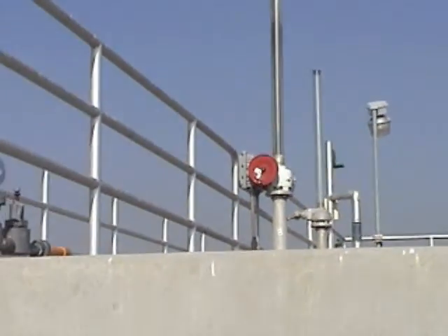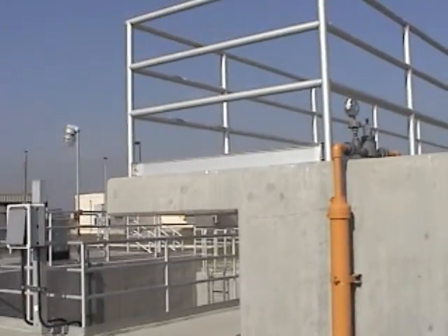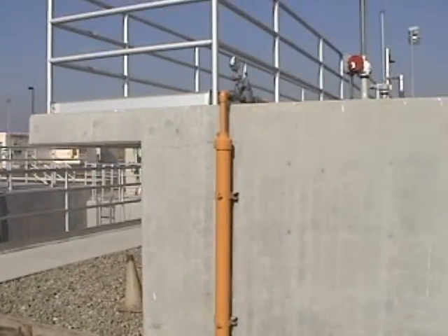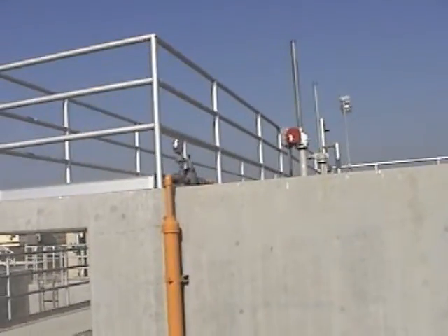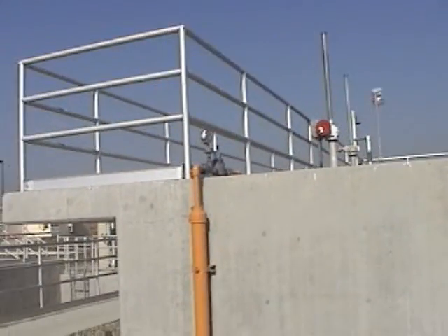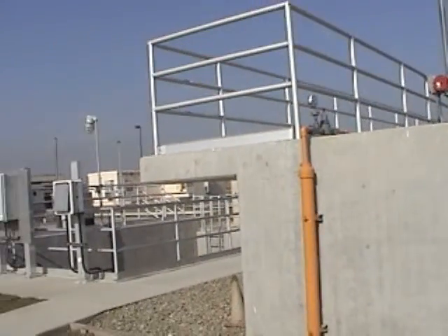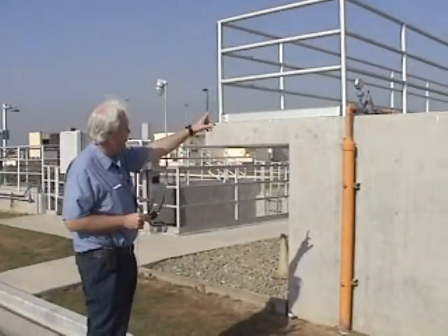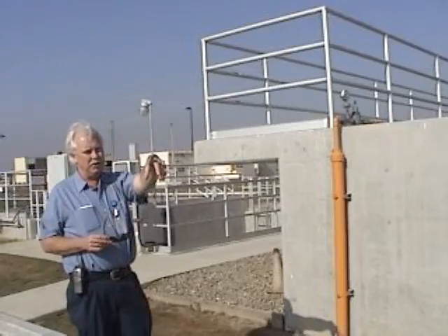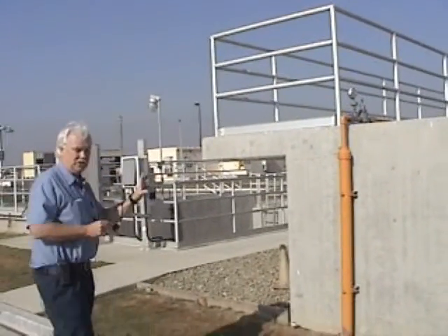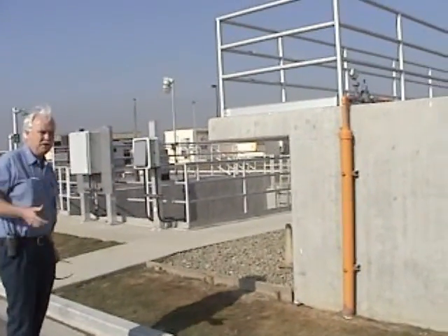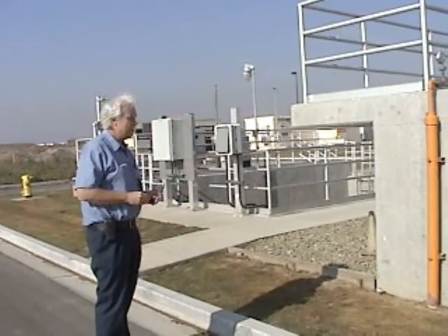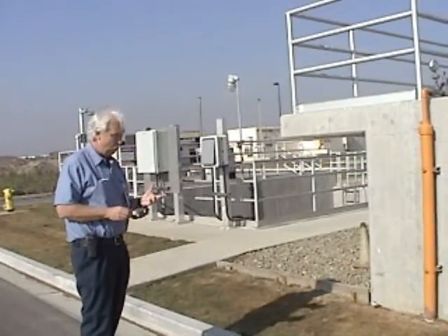But again, when you have a situation like that, where you're dechlorinating with just the back end of the tank, you really want to watch that very, very closely. You want to really talk it over with everybody, and you're probably better off shutting that gate, bypassing your flow to the lagoon and dealing with the problem. But if for some reason the lagoon were full or something like that and you had to do it, that would be something you really want to watch very, very closely.